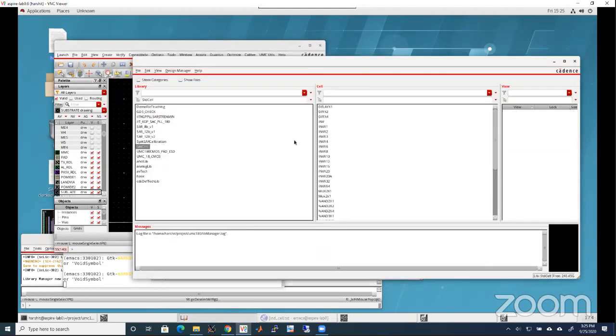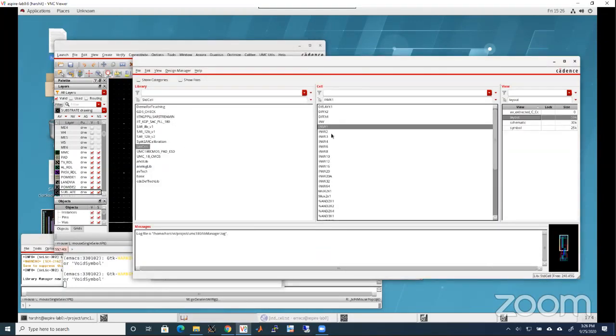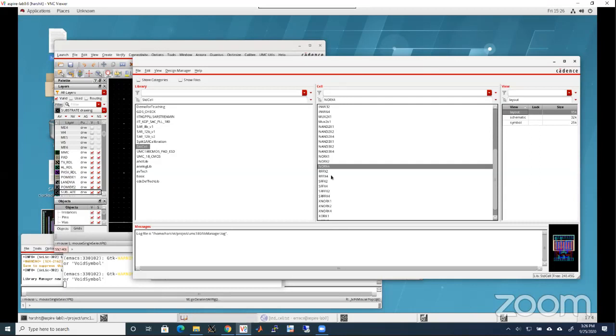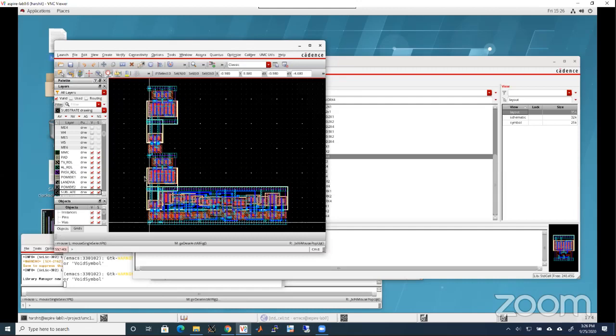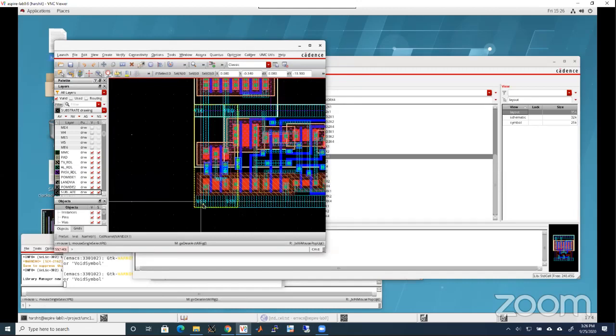Okay, a few things now. Please keep in mind, please take a note of the standard cell, how it is done. So you start out with inverter X1, X2, X4, then similarly NAND X1, X2, X4, NOR X1, X2, X4, then flip-flops, XOR, XNOR. You can do other gates also. In the layout, the power rails are VSS and VDD.